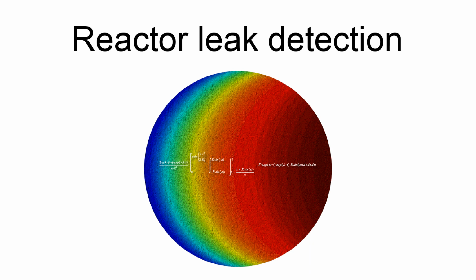Step changes in reactor coolant leakage can be detected with moving filter media to satisfy the quantitative requirements of US NRC Regulatory Guide 1.45. See description for US Patent Number 5,343,046, 1994. The mathematical method is highly detailed and it focuses on time-dependent collected activity, rather than concentration, as a function of time. The method, among other features, yields the desired result for a fixed filter, in which case filter paper velocity equals 0.